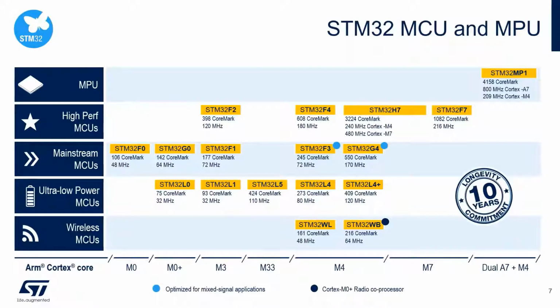So here you have an overview of our hardware portfolio, which ranges from Cortex M0s up to Cortex A7 now. In general, I would say all our STM32 could run a user interface. So the choice here really comes down to what kind of display you want to use, what is the resolution, what is the color depth, the need of animation, full screen transition, and of course together with the required application and the operating system and so on.